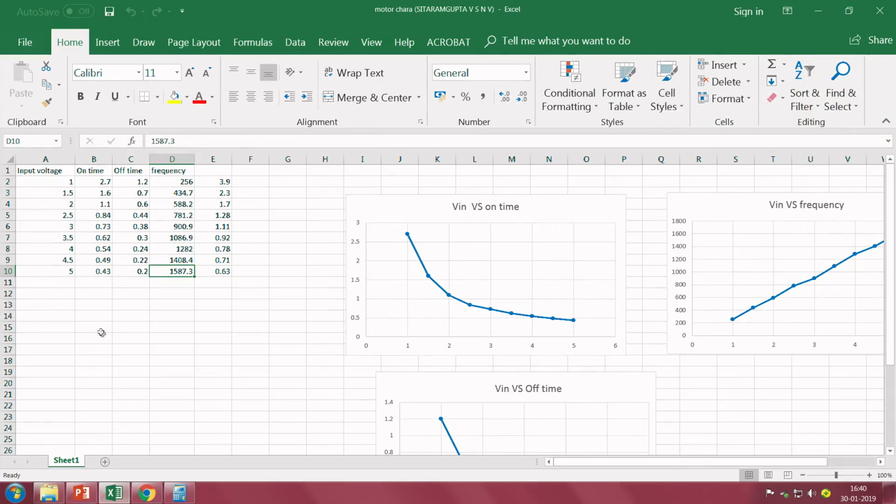The reason is that when we look into the signal, it is clear that no matter what, your on time as well as off time is always fluctuating with respect to time. So, if I directly integrate the output of the encoder without using a monostable multivibrator, it is very difficult to analyze. You may get an analog output voltage, but it is very difficult to correlate with respect to the RPM, because the on time as well as off time keeps on varying. What if we fix at any one particular value?